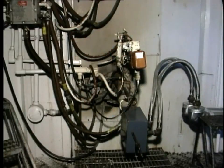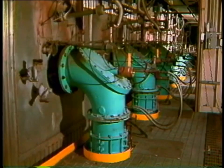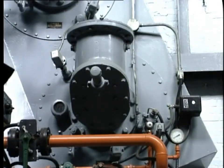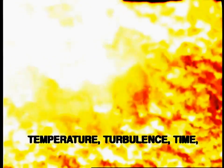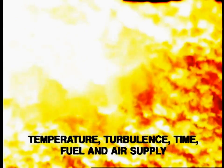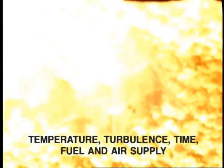Now, there are many different types of burner equipment installed, generally for different fuels, and perhaps for different grades of the same fuel. As we study these various types of burners, we should keep in mind that the objective in all cases is to provide the correct conditions for combustion, that is, temperature, turbulence, and time, and also to provide control over the supply and distribution of fuel and air.